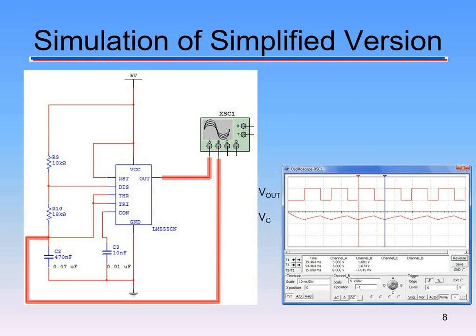So when we analyze that down, what does that really look like? We want to look at the signal. If we have the oscilloscope on here, we're looking at the input signal versus the output signal. VC, the voltage across the capacitor, versus the output voltage of the 555 timer. Notice when the voltage across the capacitor is dissipating, the output voltage of the clock is 0. I'm looking at the oscilloscope on the right. When VC is charging, the output of the 555 timer, our clock output, is high.